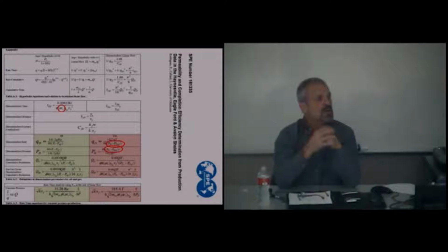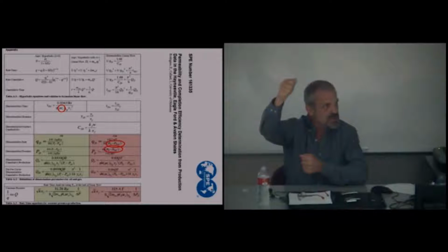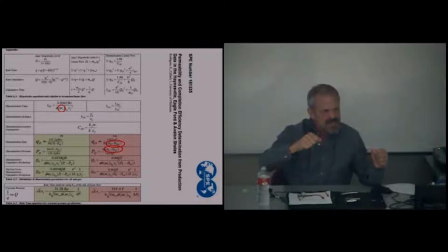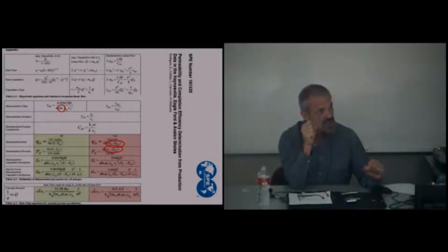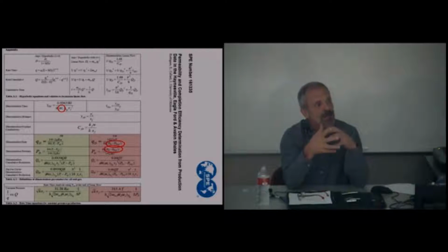Now, he was running water through that. And so he found that the rate was proportional to the pressure difference, okay? Now, if we're doing that with gas instead of water, it's no longer proportional to the pressure difference. But if we augment pressure to account for changes in viscosity and changes in compressibility, we can get this new term, pseudopressure, that now obeys Darcy's law. So it's a back calculation of what works.